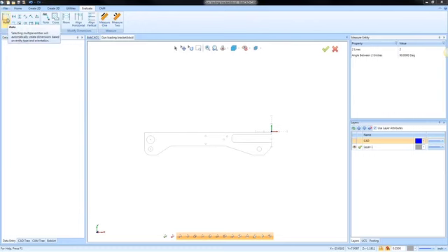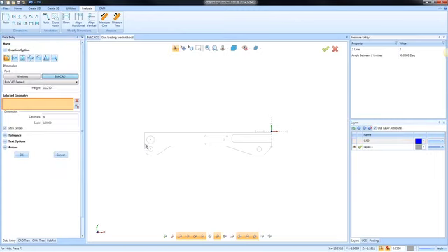The other thing we can do is use the measure auto or evaluate auto. This is a dimensioning tool. With this dimensioning tool, you can click on any of the entities. Now, here's the thing. I've noticed it's a little sticky with this, like the placement of the text. So what I do is I'll click on the line, I'll move it where I want it to be, spacebar, and then it locks it in, okay?